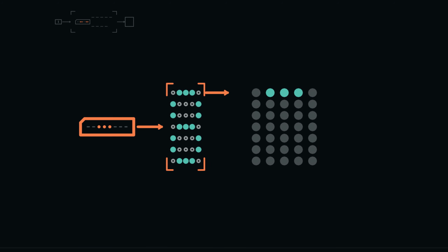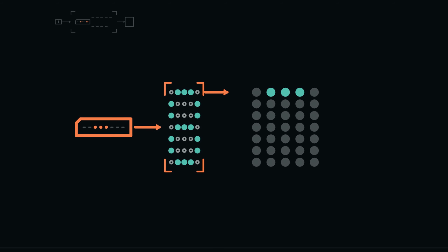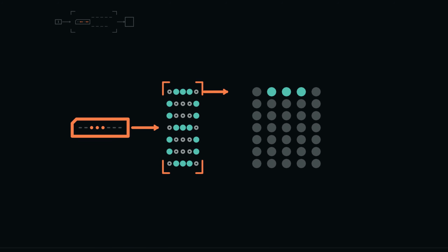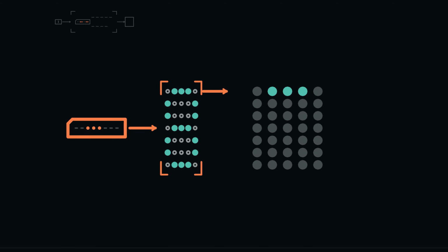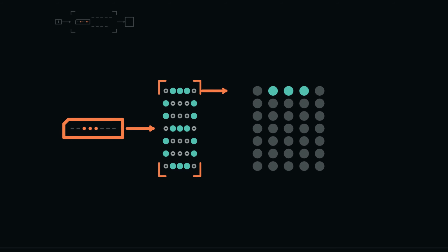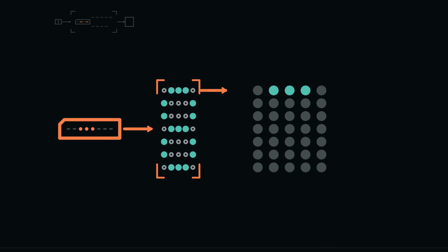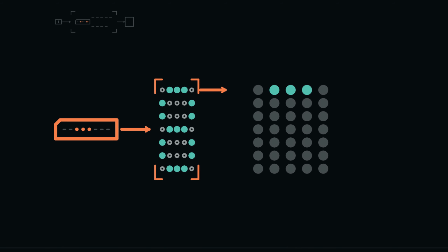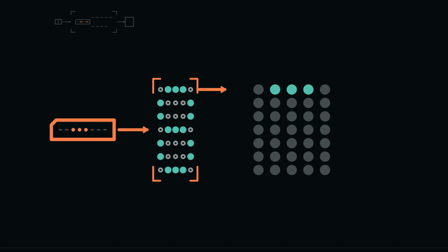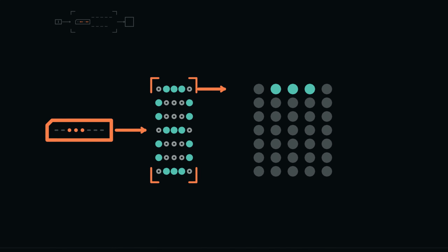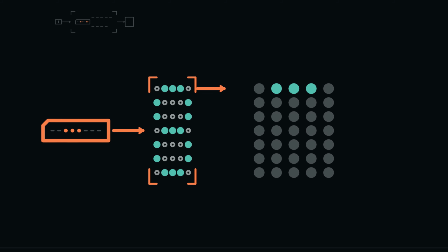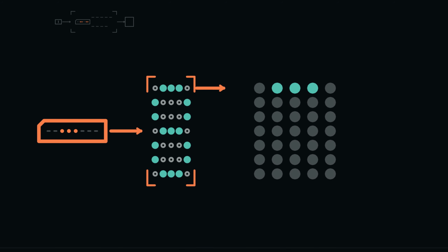Each returned font row is an ordered pixel mask. Position 0 controls one horizontal location, position 1 the next, and so on across the row. A 1 requests the foreground state at that position. A 0 requests the background state. The next stored row controls the next vertical line. Keeping row order and bit order visible is essential. The same count of ones placed in different positions would draw a different shape.